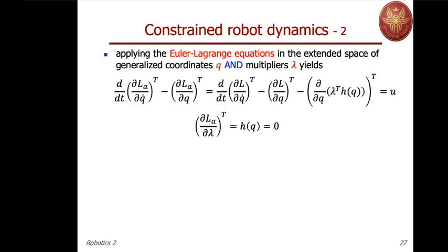And this is again finding back the original constraint. Now the minus sign can be eliminated because this is equal to 0, but you can also interpret the fact that on the right hand side you have a 0 because the contact forces, namely the lambda, produce no work. So they are there only to react to attempts to violate the constraint, but they don't produce any motion. So on the right hand side in the Euler-Lagrange equation you will have a 0.